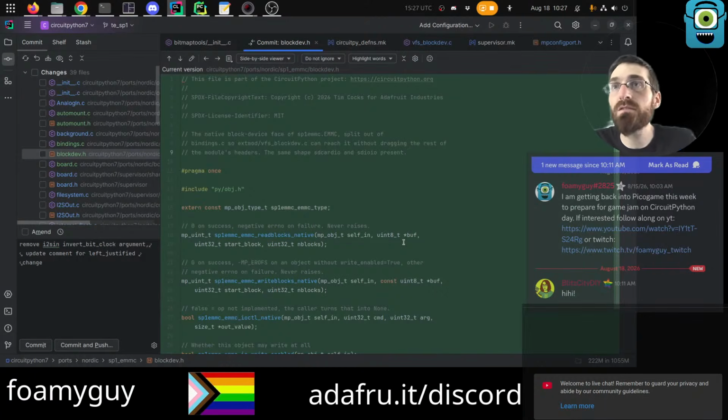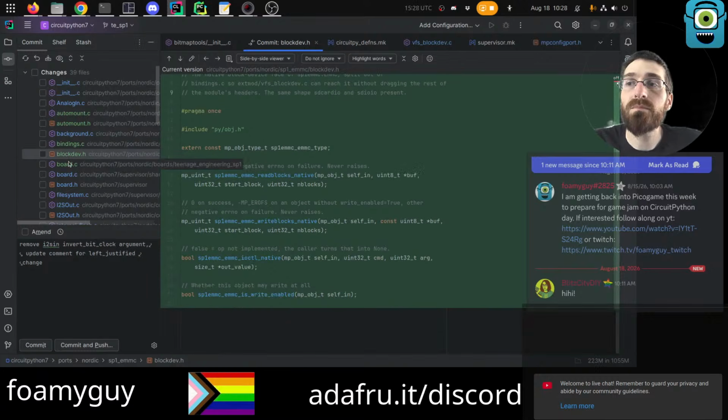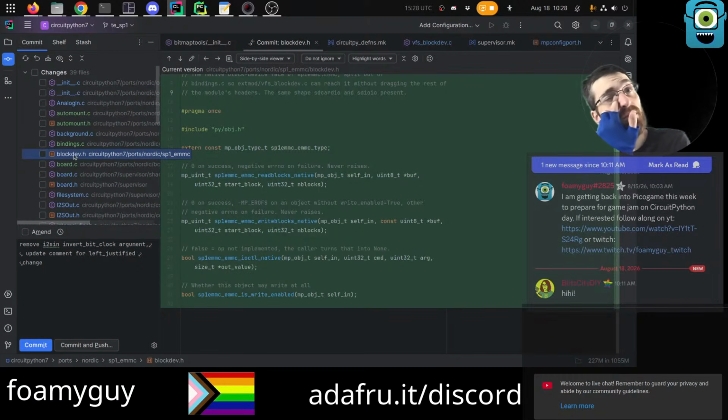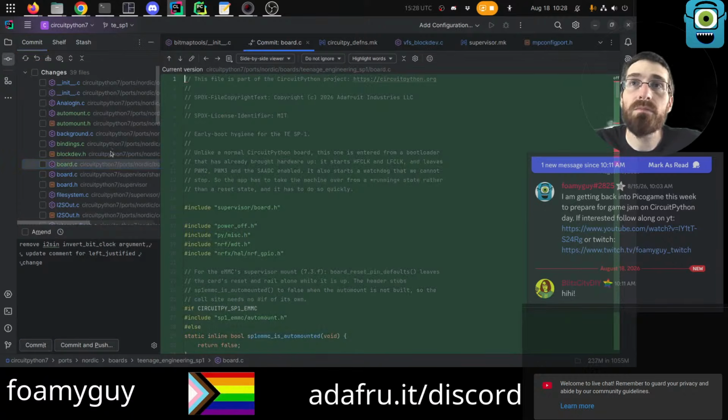It initializes itself internally, and it's writable to the host, not the CircuitPython. But in your boot.py, you could swap it the other way, or code.py, actually, I think, as well. Maybe. I think you could do it in either, but you would also need the settings.toml thing to disable the auto mount of it, I believe.